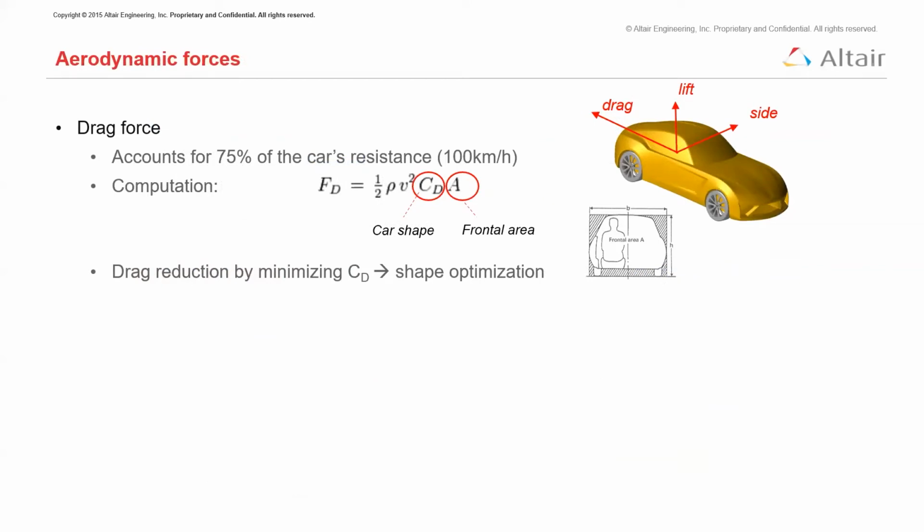So here I'm probably preaching to the choir on this slide. But we know that drag force is very important. It accounts for roughly 75 to 80% of our total car resistance, of our vehicle performance. The simple drag equation that you see there is what we learned day one in aero engineering. It's 1/2 rho v squared times your CdA, rho being the density of your fluid domain, v being the velocity of your vehicle body relative to that fluid domain, the fluid outside of it. And your drag coefficient and your area are the two values that you're really controlling when you design your car.